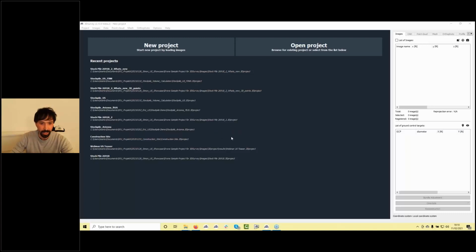Okay, you had mentioned that 10 control points per battery on a non-RTK was recommended. How many would you suggest? Okay, Eric, I already explained this one in the previous one. For the RTK, I would put 4 ground control points on all corners. This gives you independent accuracy and super accurate results. If you have a muddy area, or there's water, or you have a garbage dump, place at least 1 ground control point where you start with the drone, and I'm sure you will get the accuracy in the 99%. But as a surveyor, you always try to have independent accuracies, so place 4 of them.